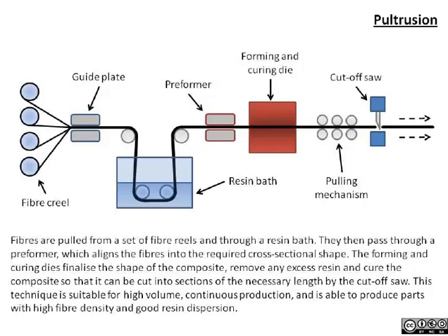We preform it. This is usually all done under a certain amount of tension, and then the composite is actually achieved as that assembly of fibers and uncured matrix polymer goes through usually an oven and cures, and then you have an actual composite once the matrix cures. Typically cured by heat or by time from immersion in the resin bath with a catalyst. UV is an option depending on the resin type and how thick it is.